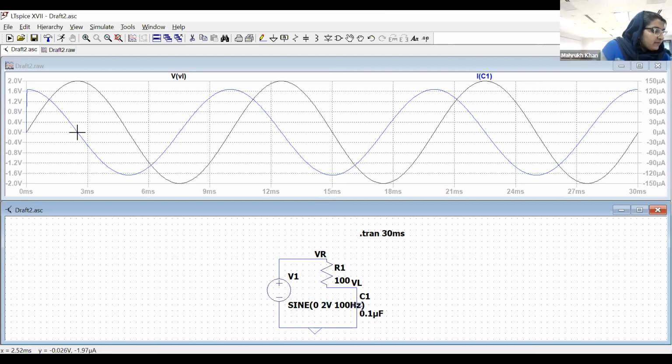Okay, so you just have to fill this table by changing the frequency, and you will find XC with your circuit and your calculations, and draw the graph. Sounds good? Yeah, I think so. Okay. Just keep in mind that here they are talking about peak to peak voltage. Peak to peak voltage is 2 multiplied by your peak voltage. So if you have 2 volts peak, peak to peak will be 4. So that's about it, I think.